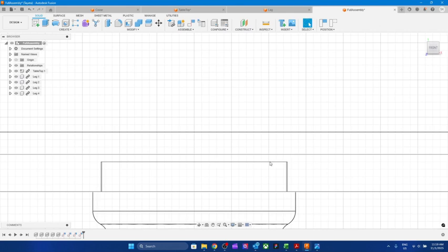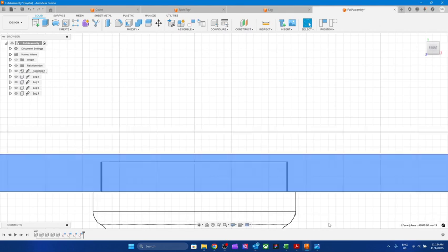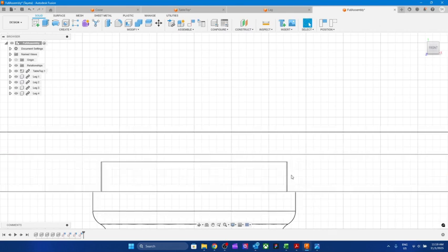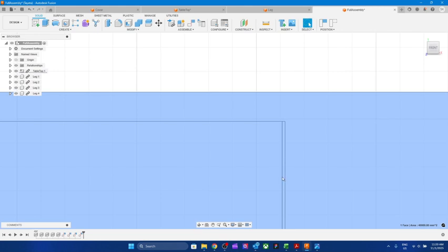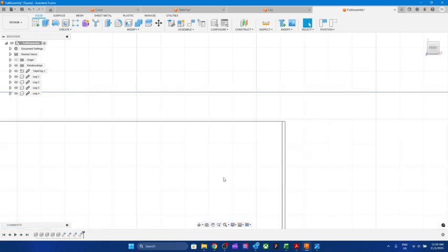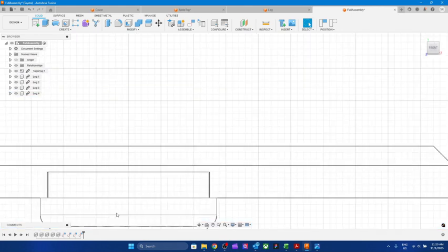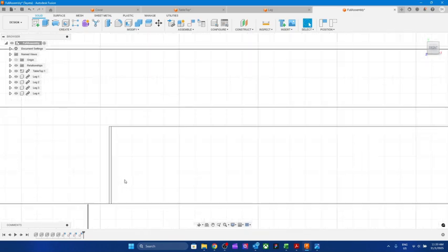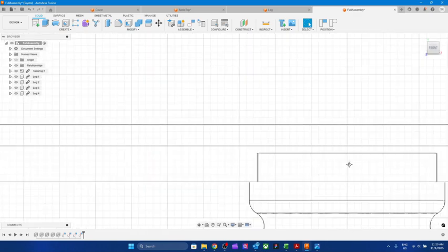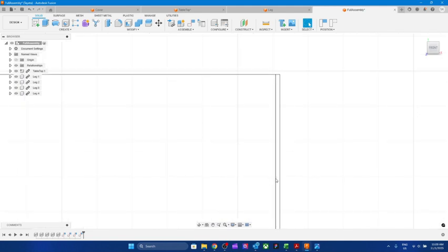Because it is aligned with this face, the top face, and the diameter. So it looks at the center. So center of this circle and center of this circle, cylinder. So centers are aligned, and that's why it will show this 0.25 gap on both sides. So this is 0.5 gap that we left. So this is 0.25 and this is 0.25, right? That gives 0.5 gap, and it's good, easy for installation.